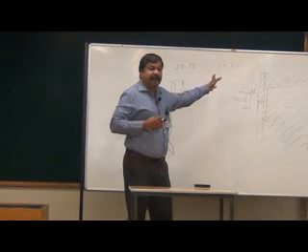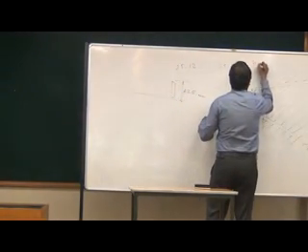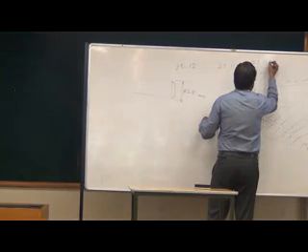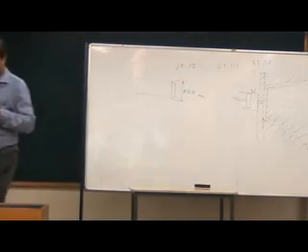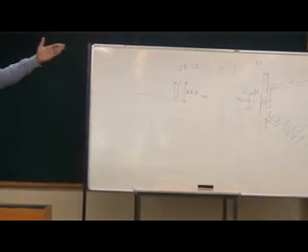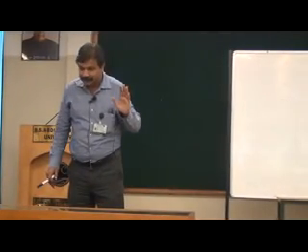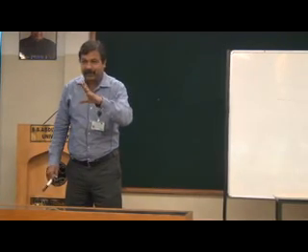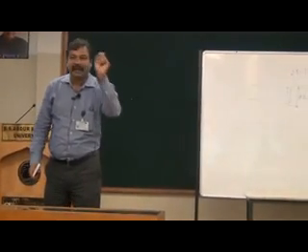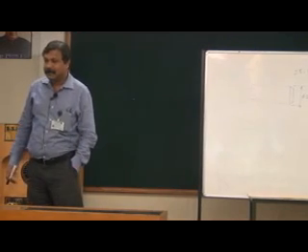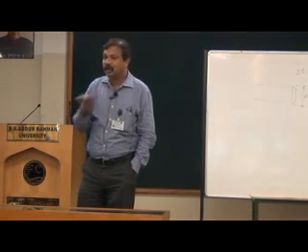If I measure the diameter with much more accurate equipment, the diameter will be 25.110. If I find even more accurate equipment, the diameter will be something else. Are you able to appreciate my point? There is nothing called an exact 25 mm diameter. It depends on the accuracy with which you want to measure it.